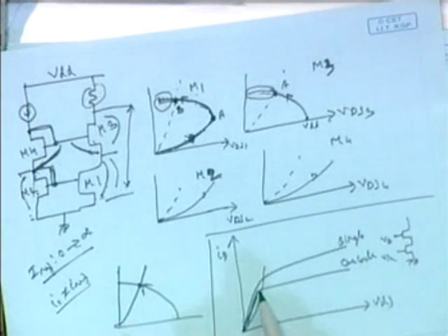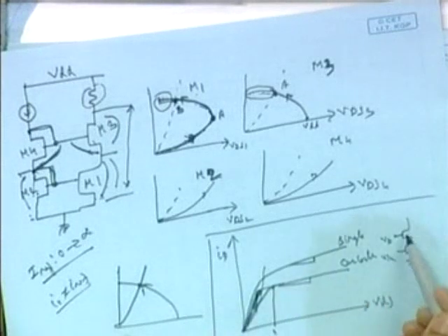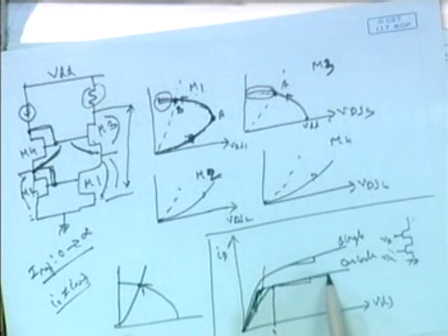You see that the effective resistance is much higher, and this will be like this. Also, this minimum overdrive voltage is larger for the cascoded structure. So if you do any simulation of the cascoded IV, you will get a flatter curve here, with a higher overdrive voltage.